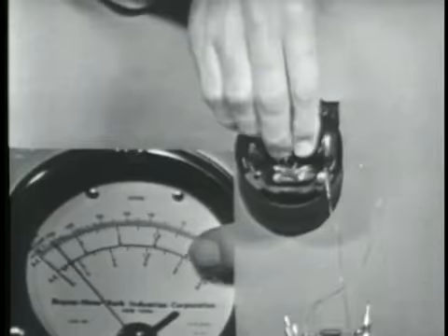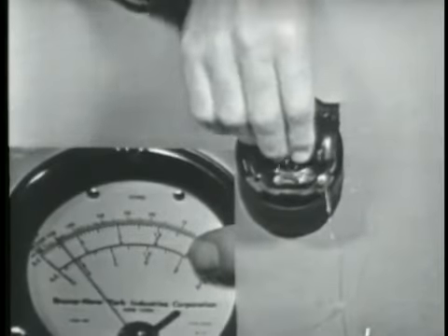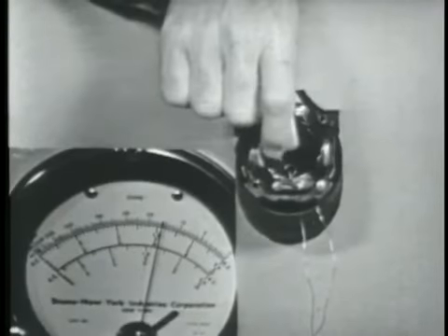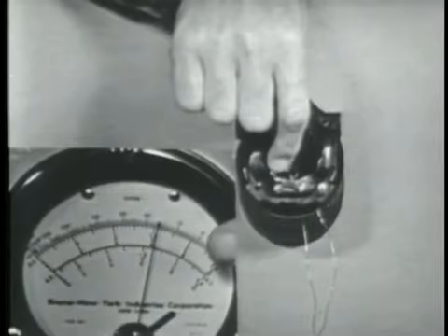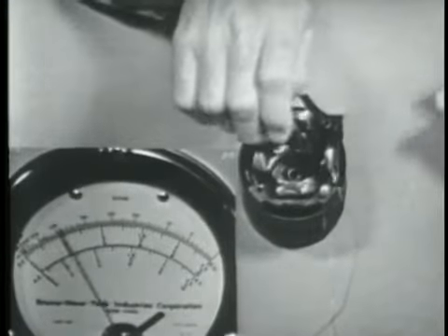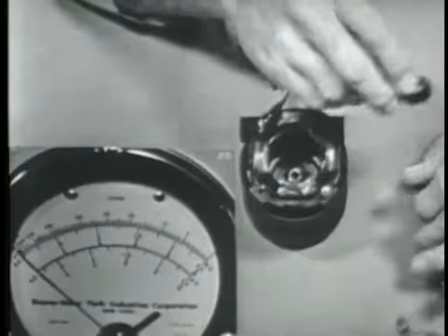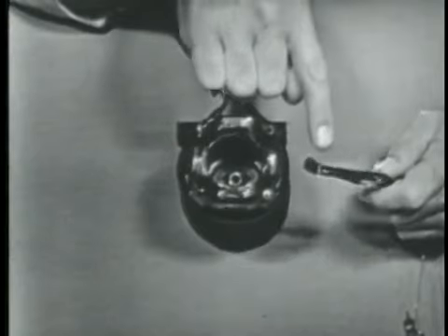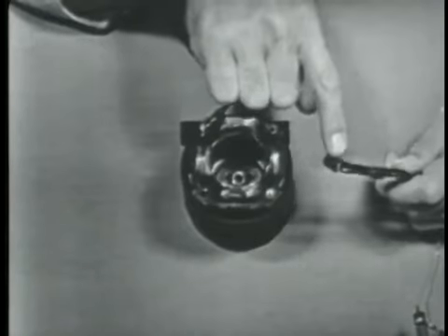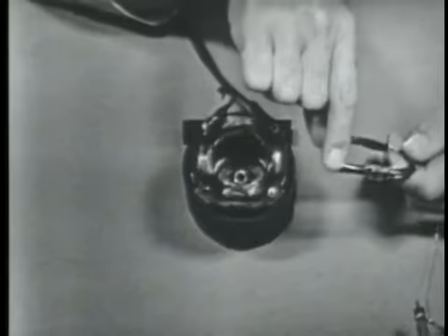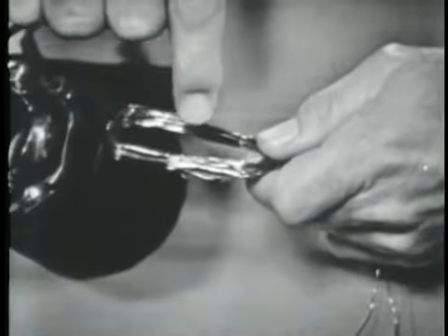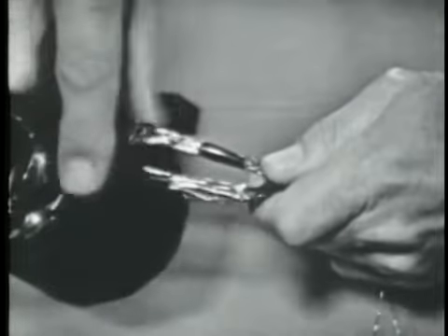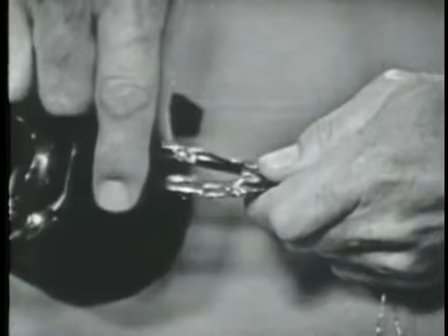And you can see that I take the loop out, it goes away, put the loop back in. I've got to get the loop all the way down in there. There you go. Now we have the rotating magnetic field inducing a voltage into the loop, which we're reading on the PSM6. Now the important thing to realize here is that once we get a current flow in this loop of wire, we have a magnetic field established about the loop. Now this means that we'll exhibit a north pole on one side and a south pole on the other. Or in other words, we have magnetized the loop. Made it an electromagnet, right?